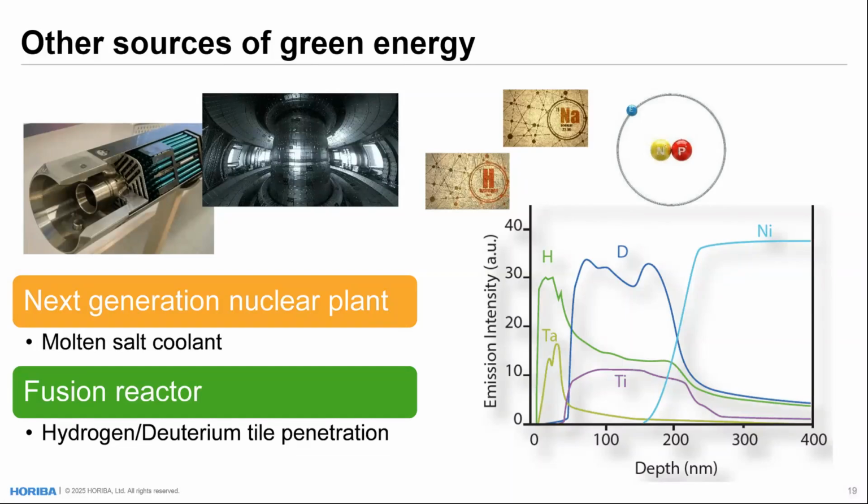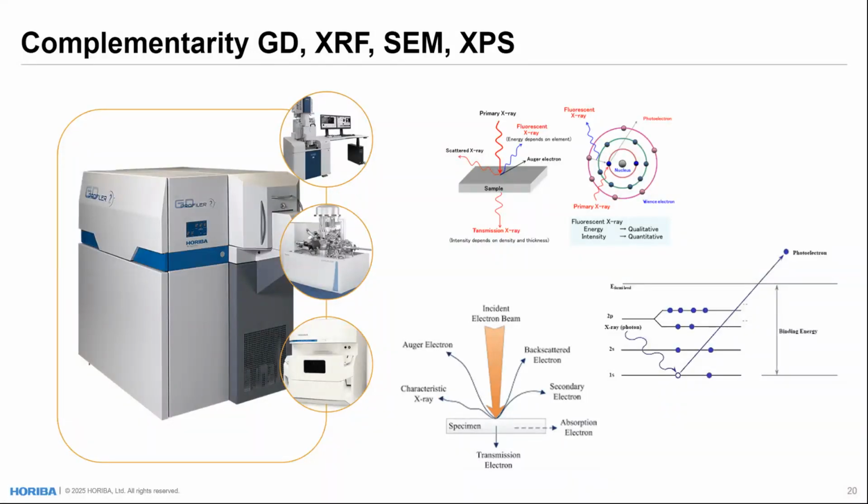And finally, I can conclude that GD-OES is an elemental depth profiling technique which complements other depth profile techniques such as XRF, SEM, XPS, or even Raman spectroscopy, which gives us some molecular information and data about the material.